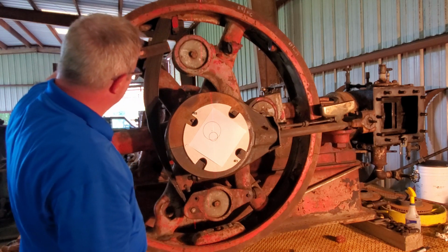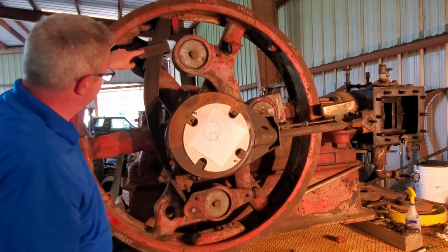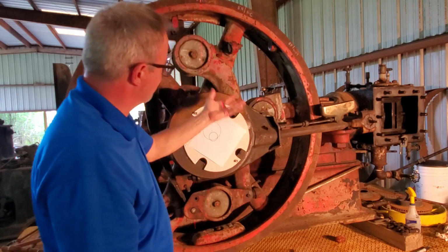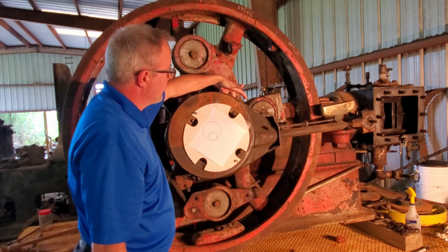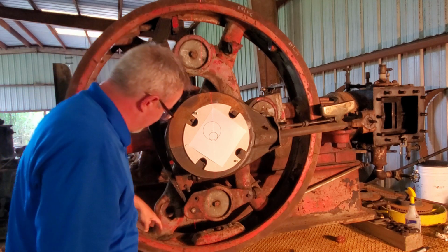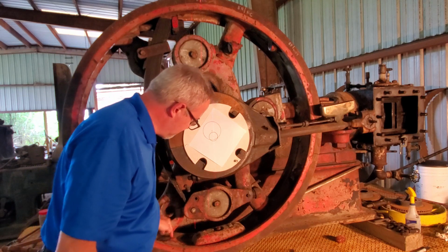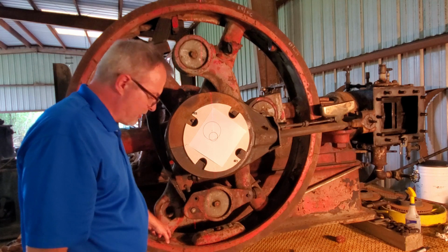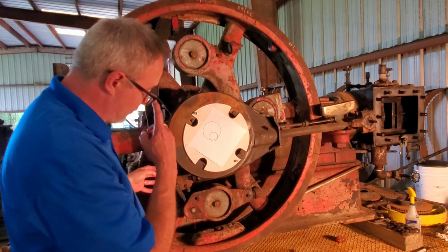That would mean that the pivot point here, which you have room for in this location, the pivot point for the spring would change. The stops would stay the same, they would just reverse. And the pivot point for the actual governor would go onto this spoke, and the tension rod would go into this boss here. Now, I'm noticing that this boss is not drilled for the tension rod for the spring. So there's a little bit more work to just flip-flop the governor in order to get the engine to run in the opposite direction.